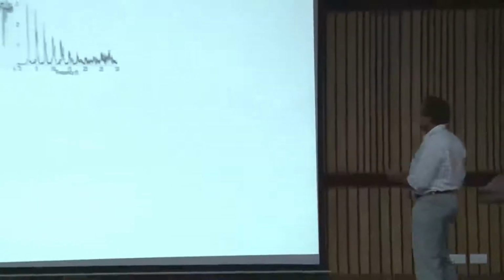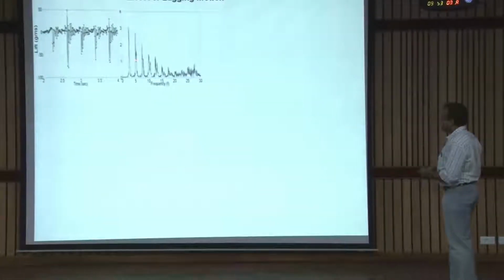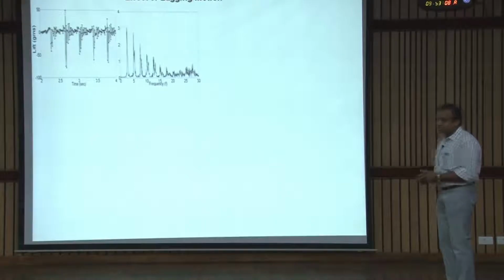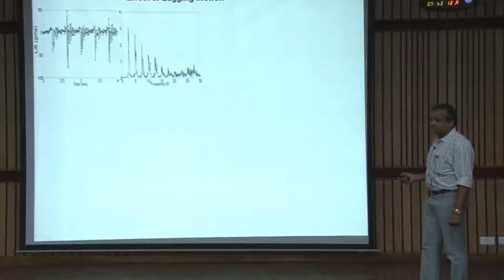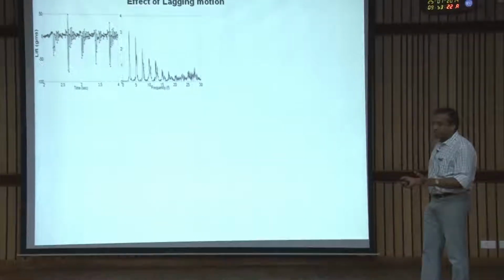So, what were those peaks? You have not shown any light on that. FFT. You have shown the FFT in the beginning. Yeah. So, if you see, these are the first few peaks, related to the vortices that you see. Vortices are present over the wing, so you will see those related to these vortices. This is the flapping frequency you see. Okay. These are some of the stray vortices that you see in the flow field.